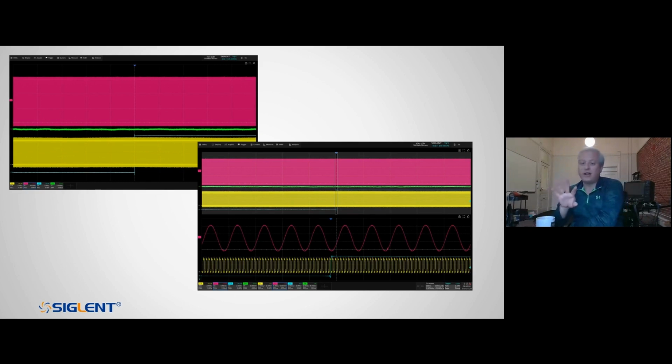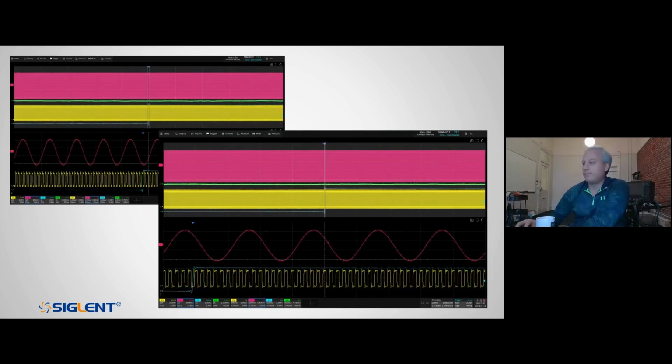So we start with the long capture on the left, in a sort of signal sequence out on the order of a millisecond per division. We need deep memory to get our high sample rate, so we can zoom in horizontally to get the right image. This you can do with almost any scope with the right amount of memory. With the combination of low noise at bandwidth and deeper memory and sampling, we can zoom in even further until we start to see a hint of a signal anomaly in the middle there.